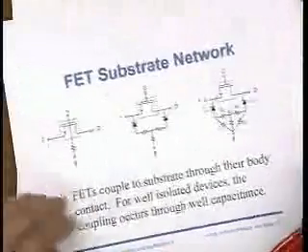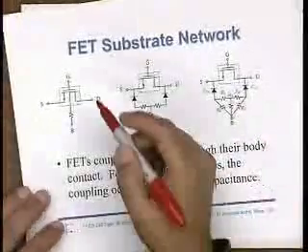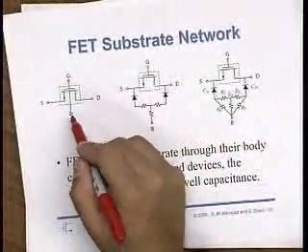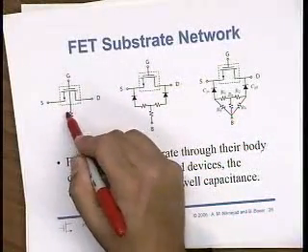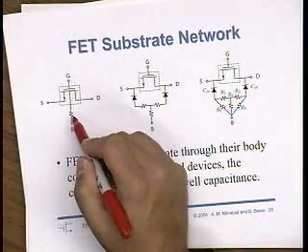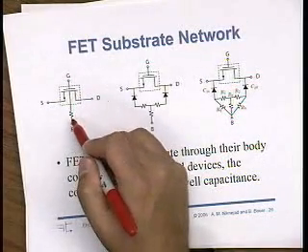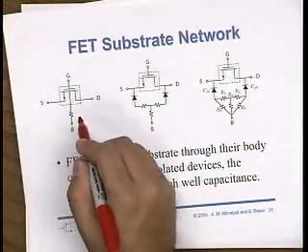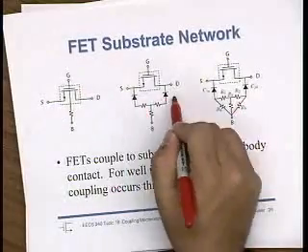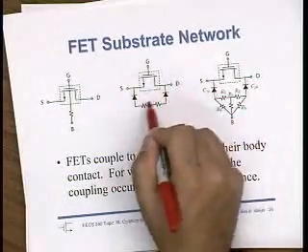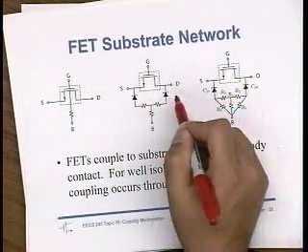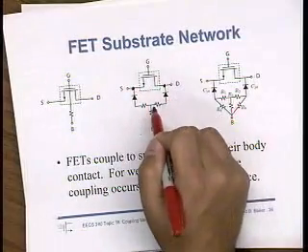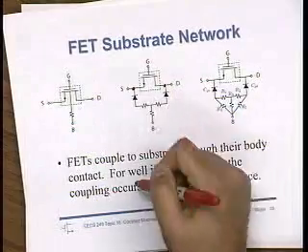All right, when you lay down transistors, you always remember there's a fourth terminal, right? That's the body of your transistor. And really the body of the transistor is either resistively connected to the substrate or capacitively connected to the substrate through the well capacitance. And the way you make contact to the body is through your source-drain junctions, right? You might think of these as external to your transistor. They're not really necessary, but they're just there, unfortunately. So every junction is capacitively isolated from the body, and the body is also connected to the substrate.